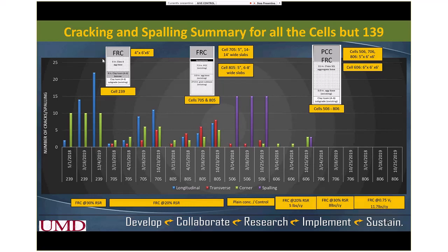So cell 239, which was 4-inch thick on a relatively weak base, also shown a crack, and 705 and 805 also shown crack. Now 705, which had larger slabs or wider slabs, has developed more longitudinal cracks, and the cell which had narrower slabs shown more transverse crack.